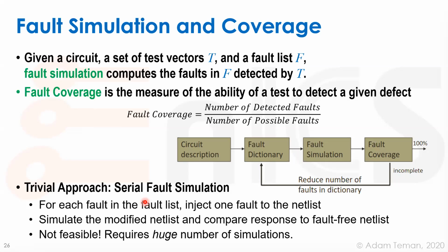Because of the cost of the scan infrastructure, in some cases you want to minimize the scan chains that you insert. And then you cover it with alternative functional tests. Okay, I didn't put that in the slide deck. They call that ad hoc DFT. If you do functional, one functional test or very few functional tests provide you with 90% of coverage. And then you can do partial scans.